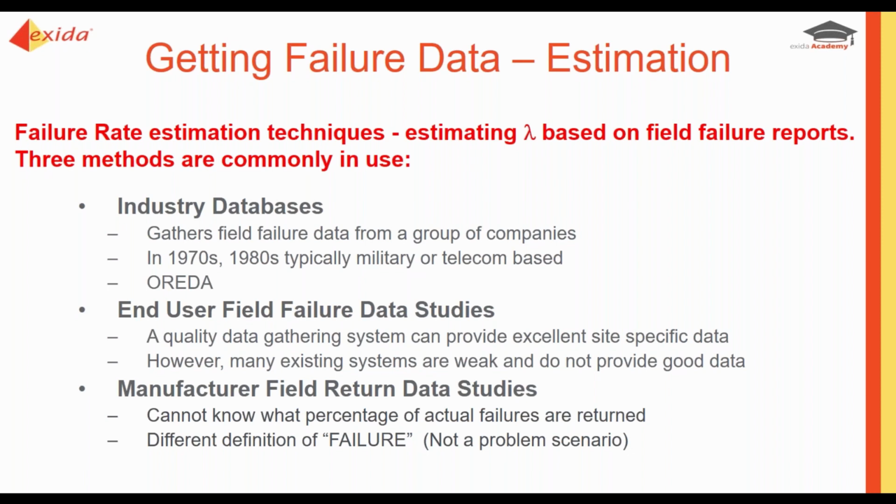Another way of estimating failure rates is manufacturer field data studies. Once again, this is great information because it's that real data. This can be for a specific device from a specific manufacturer. However, there are some bigger issues with the manufacturer field return studies. First of all, you don't know how many you're actually getting back.